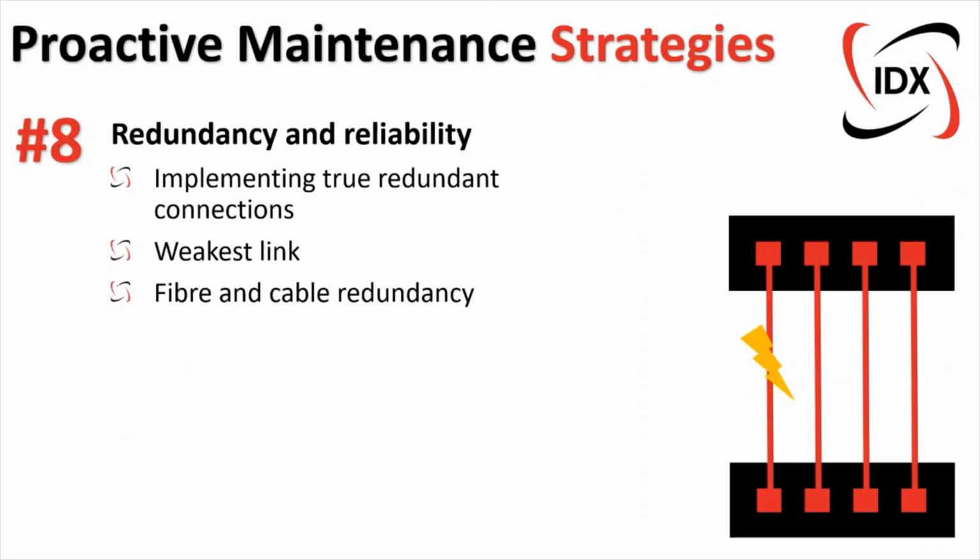An example of this is if you had to create a redundant fiber optical link. If all the OLMs connected in that optical link are not configured for the redundant link, you're going to end up causing something called duplicate telegrams traveling through the bus. The OLM will not know that it needs to drop one of its links and only communicate a message to one path. So it'll share that message through multiple paths, which is going to cause a very sure failure on the network. So ensuring that devices that are supposed to be redundant are configured properly will ensure continued health in the network as well.